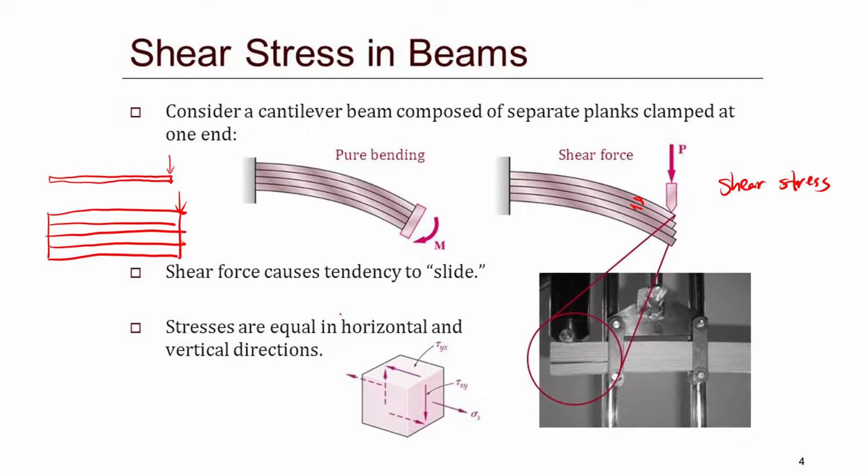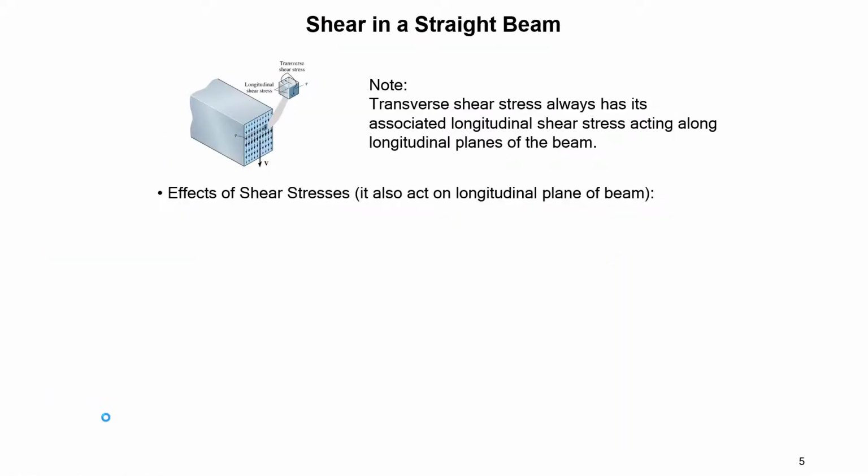And we know shear stress normally, whenever it appears, is going to have this complementary shear stress. Whenever you have this shear stress generated due to your vertical force, you must have this complementary shear stress. Okay, I think the top one should have a direction like that. So this is complementary shear stress. You always have the horizontal shear stress associated with this vertical one.